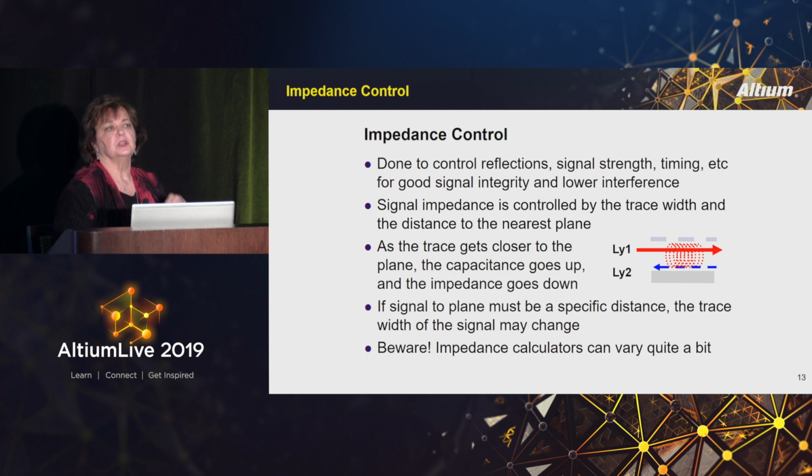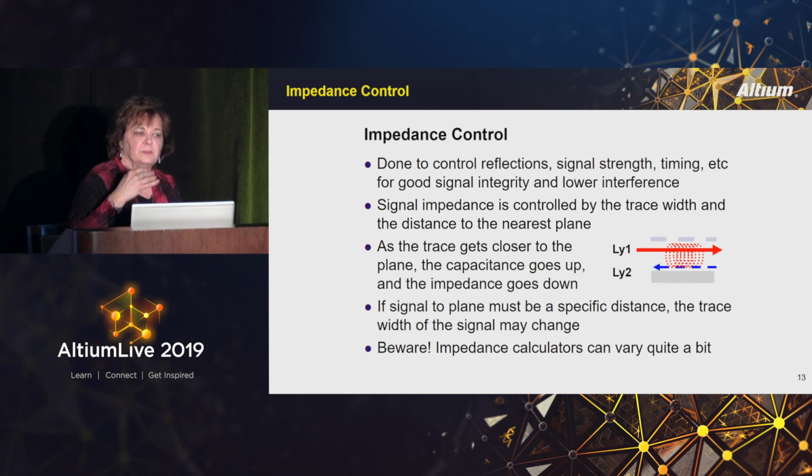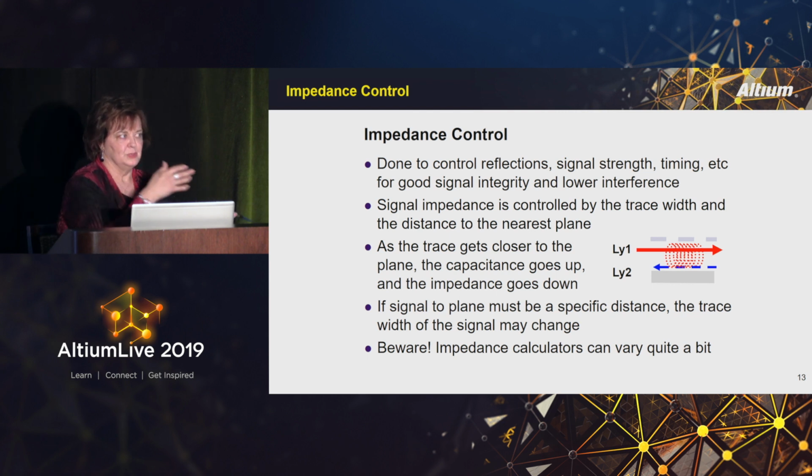So it's important to involve your fabricator in your stack-up design from day one, in my opinion. And I love what Mike said in his class, if any of you were in here. You can figure all this out in the very beginning before you ever route anything. You figure out what signals you're going to put on what layers and what impedance you want on what layers, because you can put them on separate layers if you want to. And then work it out with your fabricator. So you start it yourself, and then you work it out with your fabricator from the very beginning, and then you go forward from there, and then you don't have to go back and change anything afterwards.